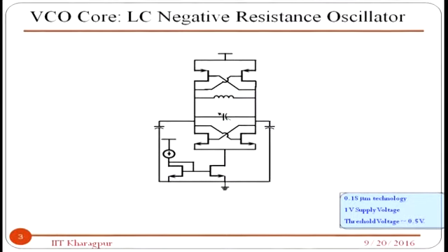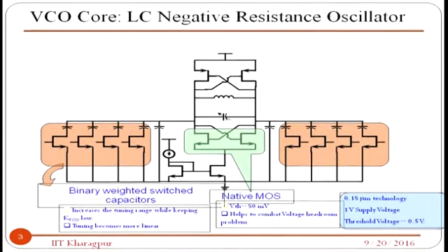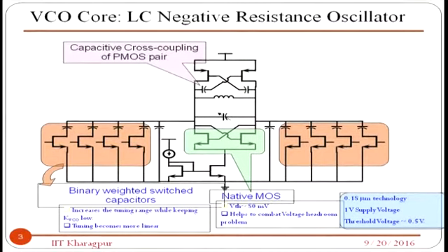Now, come to this. You are using these band select capacitors to reduce the KVCO, and then you are using another trick I would like to mention here, that the cross coupled pair is connected with a capacitor, which is a deviation from the conventional design, because it has been found that suppose there is an input swing from low to high and then going down, then you remember this voltage here will go up and the voltage here will go down, right.